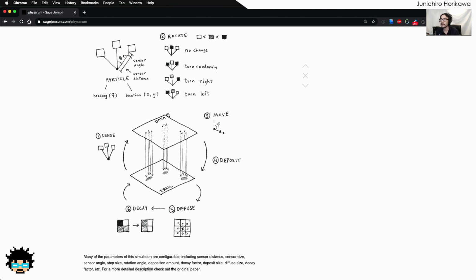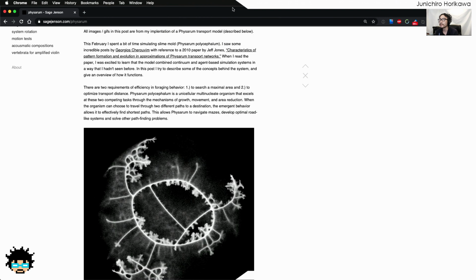What we just need to provide is 2 layers of data, the particles and the trail. Since this is a grid image, we could use a 2D grid like a plane or volume, and for particles we can just create points. I guess using volume makes sense because it gives you faster calculations when we use volume wrangle. So let's try to use volume together with points to simulate this.